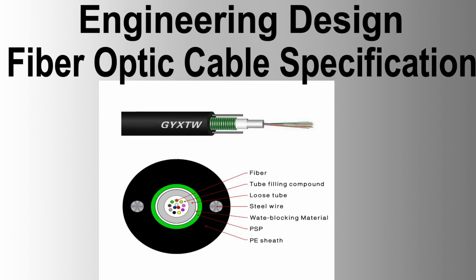General. The fiber optic cable conduit shall be laid in the same trench as the oil pipeline, positioned at the 2 o'clock position. The installation method must ensure all cable installation requirements are met, adhering to the highest standards of quality and craftsmanship in the communication industry, ensuring electrical and mechanical integrity of the connections. Manufacturer's installation procedures. Follow the manufacturer's recommended procedures at all times.